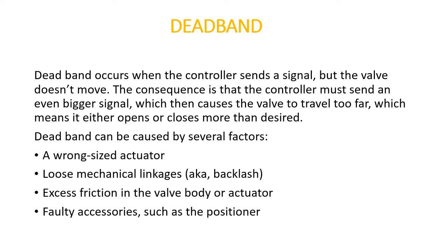So one of the common problems being faced is deadband. Deadband occurs when the controller sends a signal but the valve does not move. For example, suppose you have a control valve driven by a signal coming from the control room, a 4 to 20 milliampere signal.